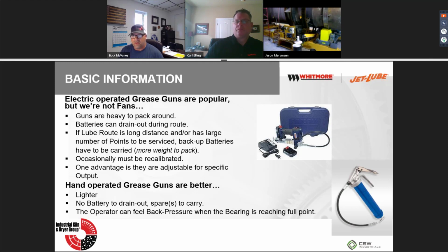What exactly are we putting into that? Yeah, and we'll go through that too. A lot of these things on the units, you can have a color-coded grease cap. You can also number these things too, and the number could be weekly, monthly, that type of thing. Just know you've got that capability when you label these things through the oil safe system and color-coded type stuff. You've got that capability of knowing when and how often you need to grease that particular bearing.